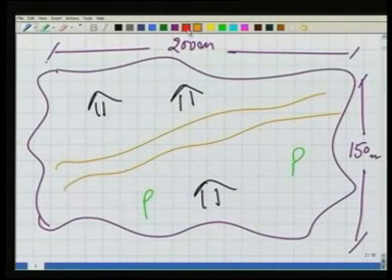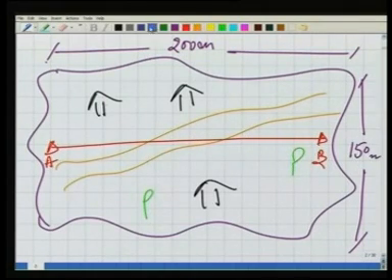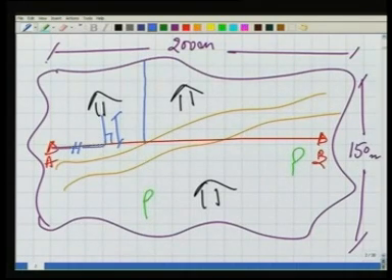If you go with the usual method, well, I stretch a tape or chain here. That's my chain line or the survey line, A and B. Conceptually it looks all right. Yes, why can't we do it? Well, we start taking the offsets and measuring the chainage. Now for this boundary here, can you guess what will be the length of the offset? The offset will be around 75 meter long.